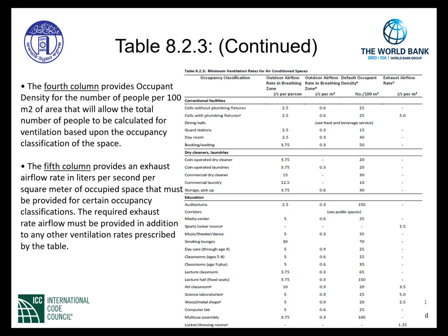As seen here in the last column, not every space or room requires an exhaust airflow rate. Some spaces do. If we look at the occupancy classification of education again, we look to the sports locker rooms.